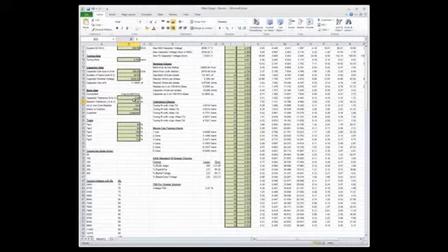I pulled out an entire row of capacitors. It was 3 of them, one per phase. I pulled out an entire row of them to basically bring the filter back into the same range that it had been designed for, which reduced the current loading on the reactors back into their nominal range. So that's one thing you may want to watch, is that when you get these things actually out there in the field and built, the capacitors will be significantly greater than 3%. Almost nobody will build you a filter with a 3% capacitor anymore.